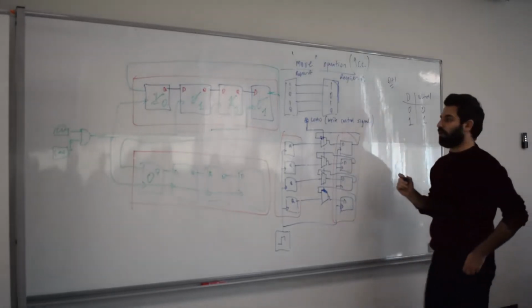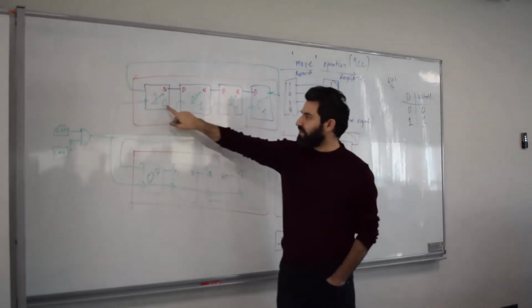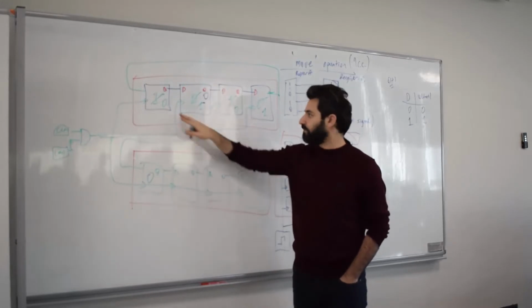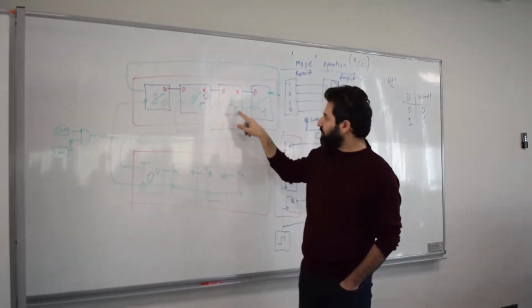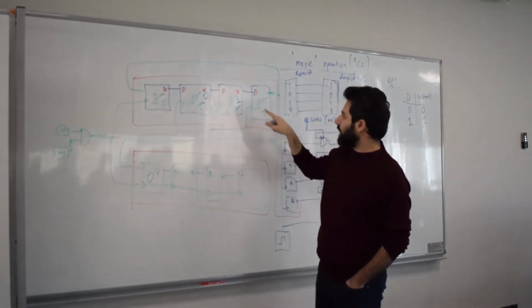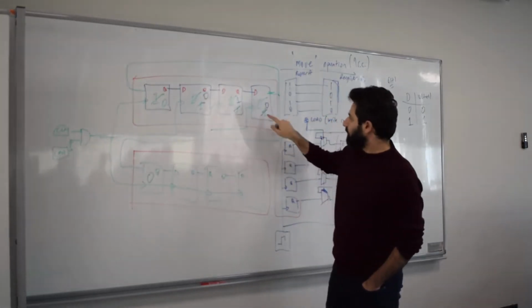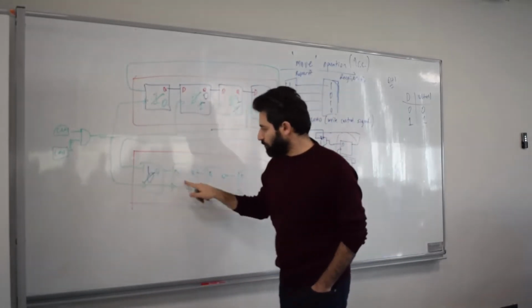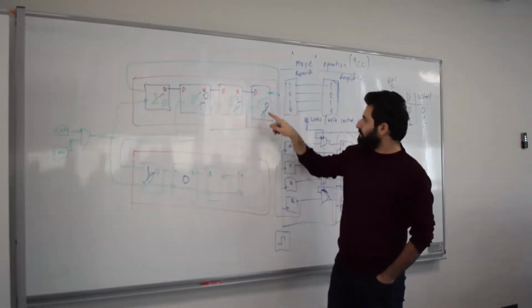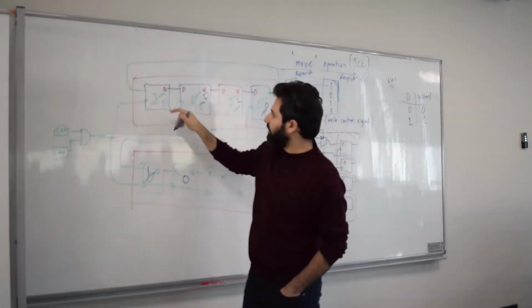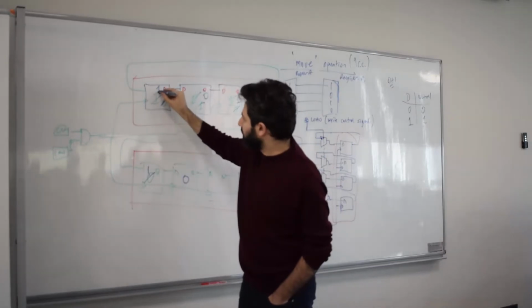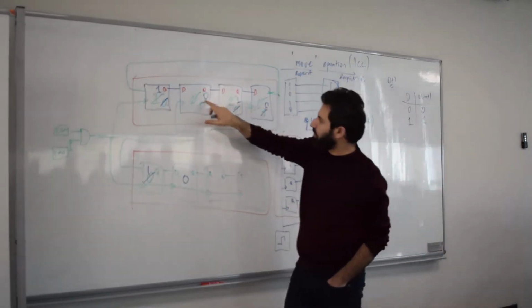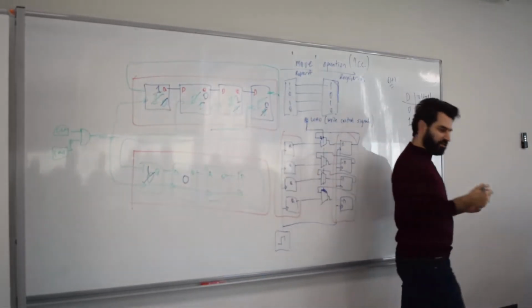What's going to happen in one more clock cycle? In the next clock cycle, this 0 will move to here, right? This 0 moves now. This 1 now moves here. This 0 now moves here. This 1 moves here, right? And this 0 moves here. How about this one, it also moves here, right? That is 1. Okay, now everybody has blue, right? Okay, good. That's the next phase of the clock cycles.